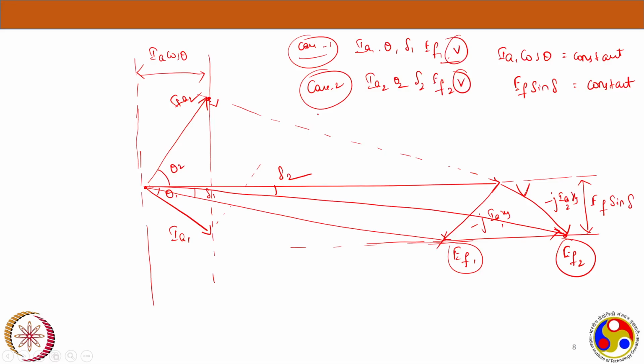So again, I'm just taking only two cases here. I think you have got the point of what I'm trying to showcase. Now for the motor case, we have seen IA cos theta and IA sin theta being held constant. We can see the two different power factor regions based on the excitation which we have provided to the motor here. So if I increase or decrease my excitation, I can vary the power factor.